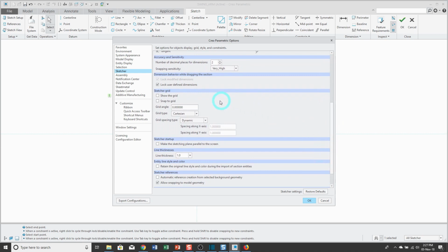Okay, let's see over here. I'm going to skip some of these different things. Oh yeah, Sketcher dimension auto lock. So here's a command that will allow you to automatically lock dimensions when you create them. And I'm hovering my mouse over here, and in the tooltip, it'll also tell you the corresponding config.pro option. In other words, this is Sketcher dimension auto lock. And here's where we have the ability to show the grid. You can see that that option is Sketcher DISP grid. And there's also the one for grid snap in here.